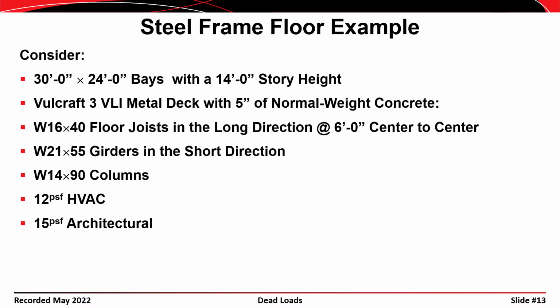We have W21x55 girders in the short direction, so they would be spaced at 30 feet. We have W14x90 columns, and we're going to design for a mechanical load of 12 pounds per square foot and an architectural load of 15 pounds per square foot.